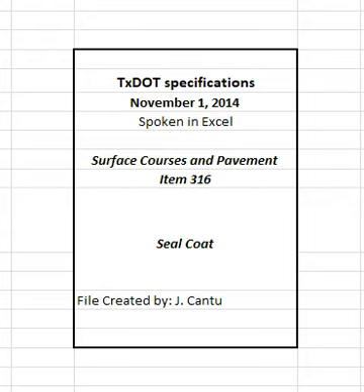4.11 Patching. Before rolling, repair spots where coverage is incomplete. Repair can be made by hand spotting or other approved method. When necessary, apply additional asphalt material to embed aggregate. 4.12 Racked-in aggregate. If specified on the plans, apply racked-in aggregate after patching, uniformly at the rate directed. The racked-in aggregate must be applied before opening the roadway or intersection to traffic. 4.13 Brooming. After rolling, sweep as soon as aggregate has sufficiently bonded to remove excess. In areas of racked-in aggregate, sweep as directed.